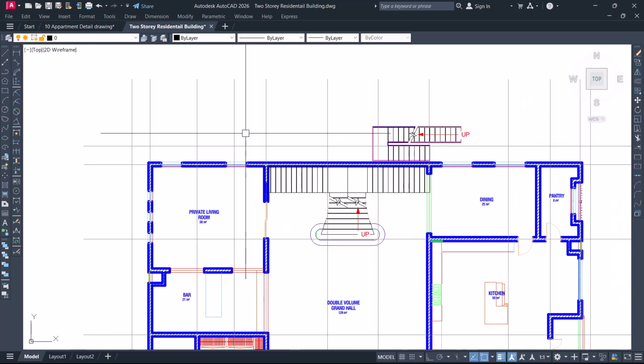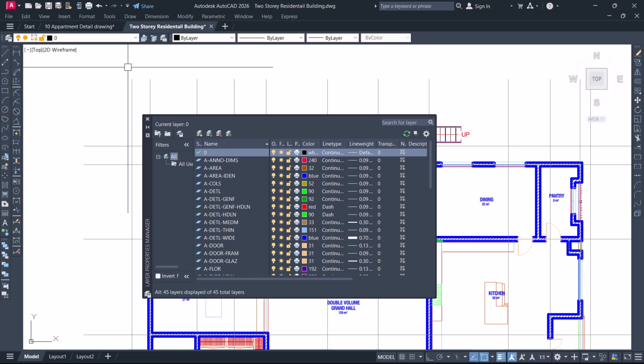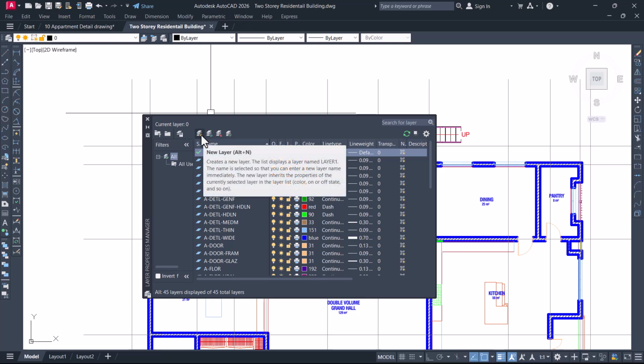Since we are using the software Protastructure for our design for this structure, we are going to create two layers before we can export this plan as our GA drawing into the software. So with that now, we are then going to create two layers. I'll type layer, and press enter key. Then I will click on new. This is to create a new layer.